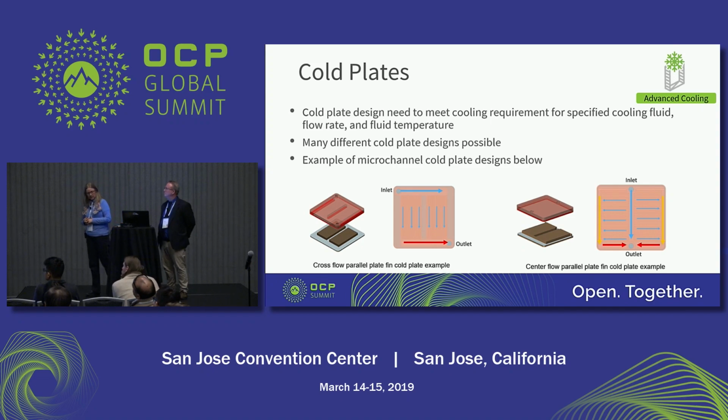And then the last ingredient, talking about the cold plates. And the cold plate design needs to, of course, meet your cooling requirements for the specific fluid that you're using, the temperature that you can provide to it, and the flow rate that you can provide. And there are many different shapes and options for cold plate designs, really.